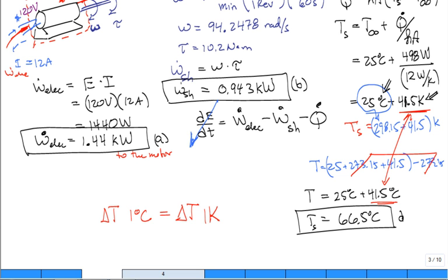I did have a question. Yes, sir. On our formula, it says that it's Q dot minus W dot, so why did... Well, just like in statics, you have a free body diagram, and that trumps the assumed direction. Without a free body diagram, if I say F of X, it's in the positive X direction. If I say F of Y, the force is in the positive Y direction. But if I've got a free body diagram, that defines the direction.